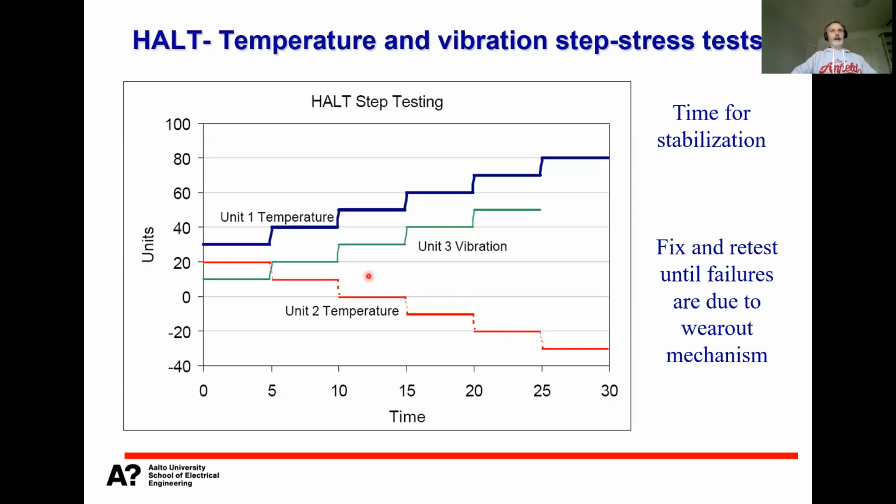You come back and do it again. So these are now the temperature step stress tests. And then you have the same with the vibration. So you start with a certain vibration level, increase, find a failure, fix it, and do it again.